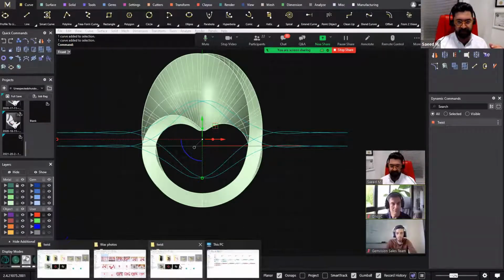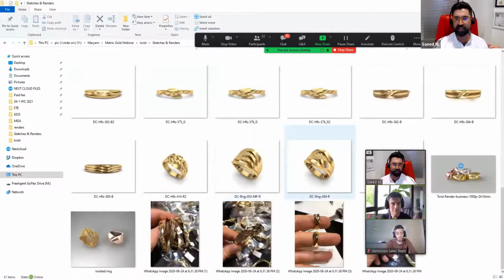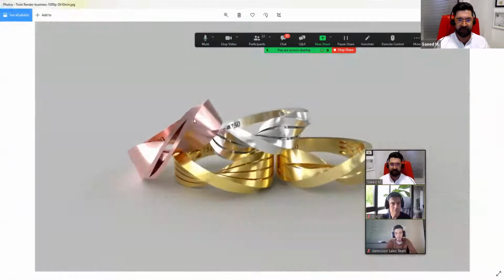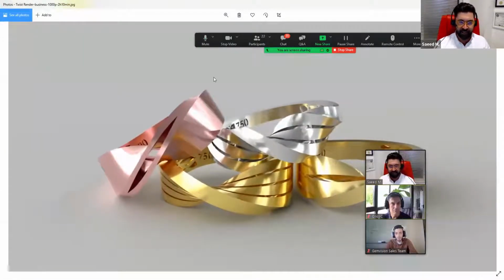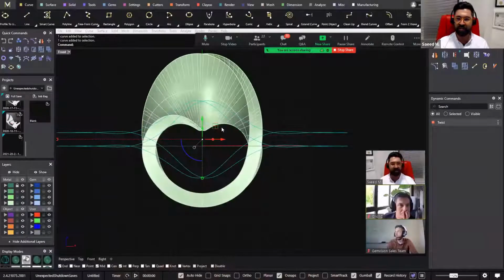As you can see in the Mobius strip, rendered with MatrixGold, there are very smooth and relaxed points and surfaces. That's because of the fewer control points. It's the big and first rule: the fewer control points you have, the smoother and nicer surfaces you get. This is the first step and first rule, and that's why I always reduce the amount of control points.